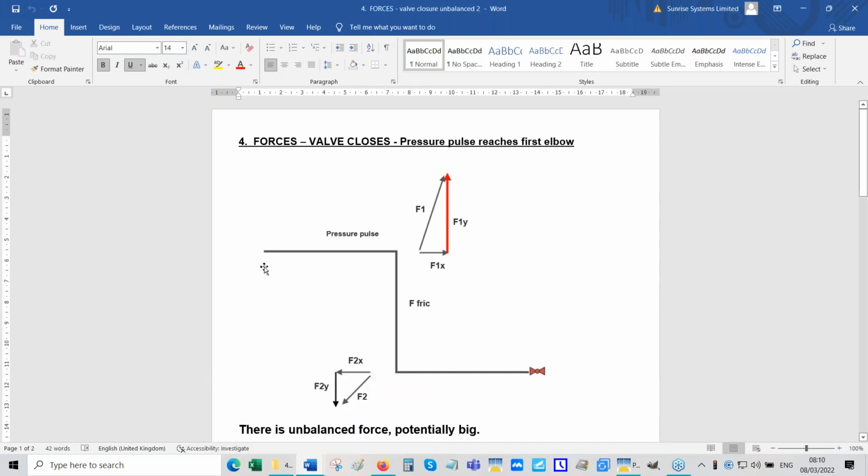See, now the position reverses when the pressure spike reaches the other elbow. That component becomes quite big, and that goes back to a smaller value. As I said, I'm considering this a little bit hypothetically in an extreme case. It will not be starkly like this. It doesn't shift from elbow to elbow quite that way because it's a wave front of the pressure. So this will not go back to a really tiny value, and that will go to a very large value. I'm just showing this for explanation purposes.